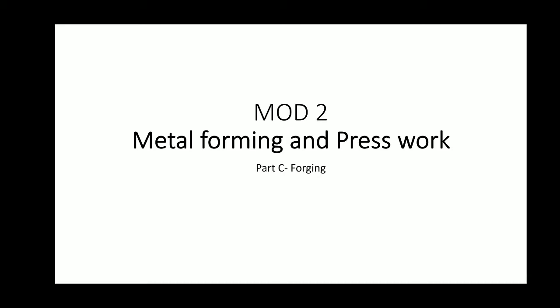We have also discussed forgeability, what the requirements are for a particular metal to undergo forging, or whether there is a crack or not during the process of compression. Definitely we have discussed those things. Similarly, we have also discussed the different forging processes, like the drawing out process and the cogging process. There we have seen the upsetting process and all.